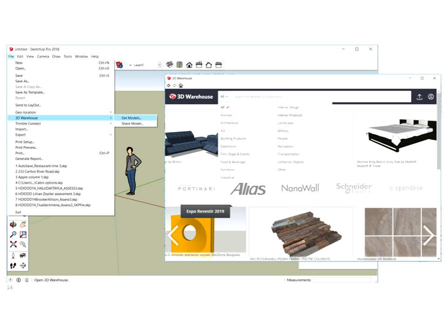Okay, just a reminder as well that when you want to populate your models, and we might get to do a bit of this in application sharing today or not, under your File menu, or that might just be the Apple symbol on a Mac, the 3D Warehouse is in there, and you can click on Get Models, where you can find a range of standard furniture, appliances, floor finishes, textures. All the big brands are in there these days. You can find a nice Bosch dishwasher or some lovely Italian Vitra sofas and other things.